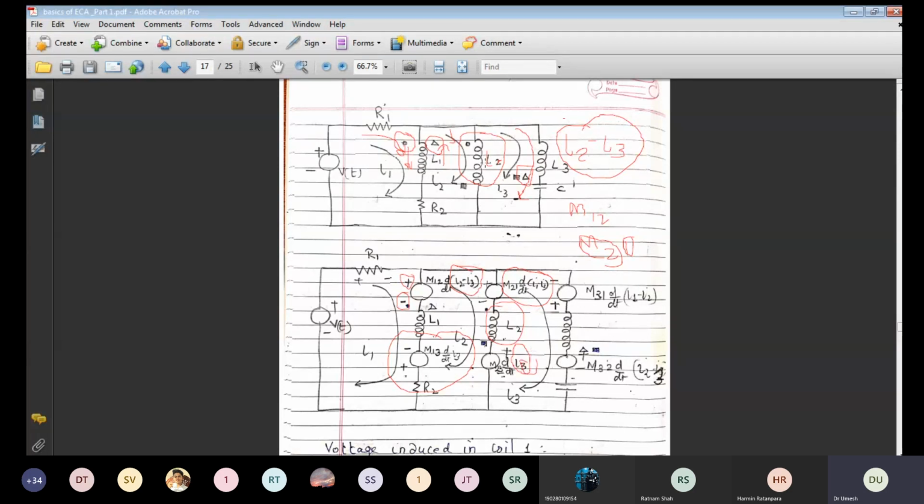And here you can observe that the current passing through the second winding is leaving. We have to observe the dot here. This is a square dot related with the square dot. So current is leaving here, and here is also current leaving at the dot. Leaving at the dot, both are equal. Leaving, entering, then we have to take plus here, minus here. Plus here and minus here.